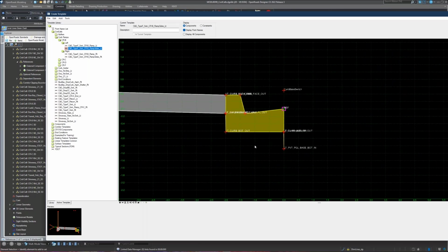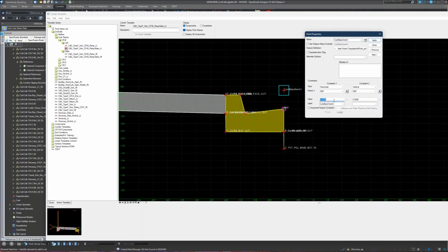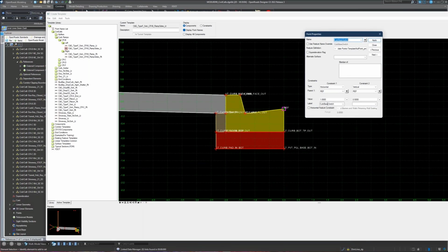And then I've also got this created so that, sometimes we have projects that have curb base. If I flick this thing on, it turns the curb base on. That's another parametric constraint right here. If you wanted to turn the curb base on, you would just add a parametric constraint and add this and say anything other than 0, basically.